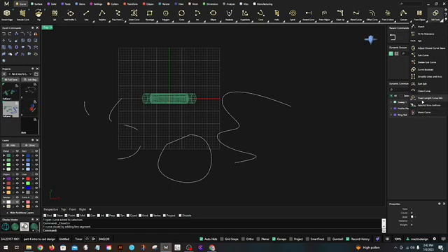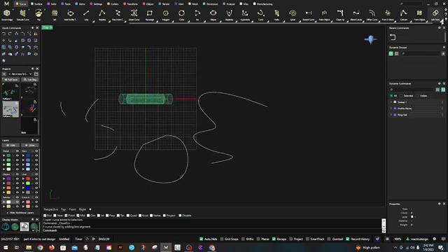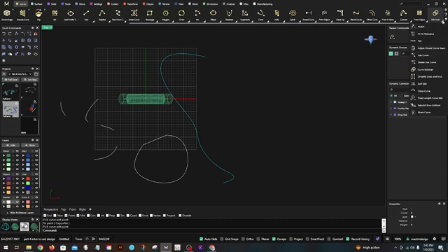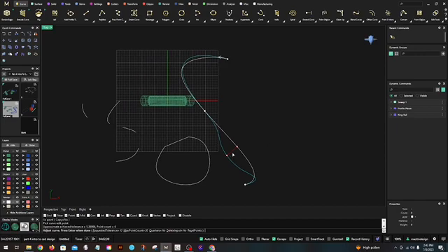Okay, fixed length curve edit. All right, let's click on that. Fixed length curve edit. Select the curve. I don't want it to copy, and I'm going to pick a curve edit point. I'm going to pick right there. Oh yeah, so that takes your length and moves it however you want. Very nice. I could see using that. That would be practical. And then rebuild non-uniform. Very nice. Okay.